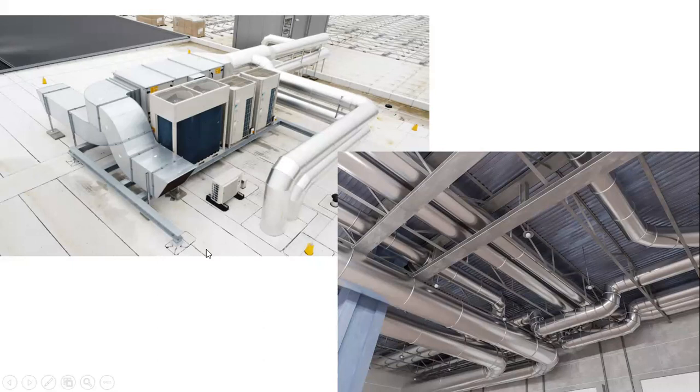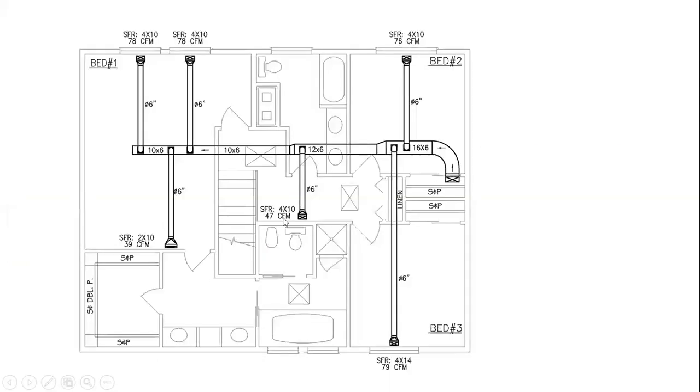So this is the third thing. And the fourth one is the 2D drawing. Usually, again, on site while doing the construction, we require the 2D drawing because, if you try to see here, airflow is given like 39 CFM, 78 CFM. This is airflow, cubic feet per minute. How much air is moving from this duct? The air conditioning is coming from the roof. If you see, it is coming from somewhere here, and then it is going down, and then we are providing the air conditioning to this architectural building, or structural building. Everything is integrated with each other.